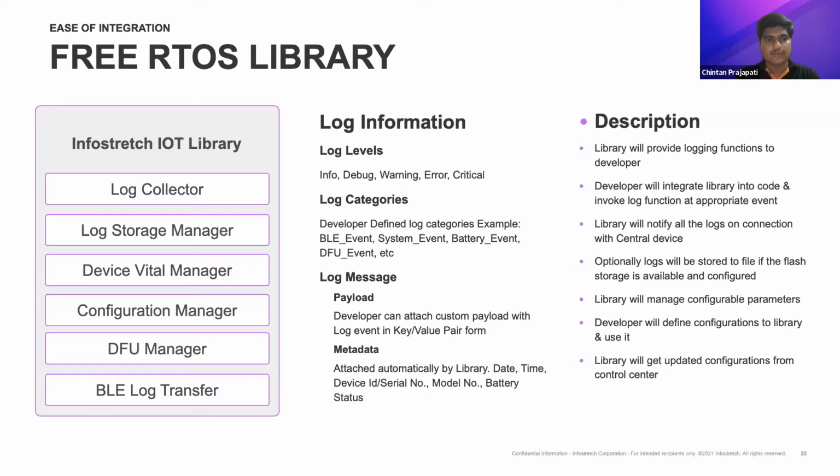Device vital manager: whenever we collect any event, this device vital manager is mainly responsible for collecting common metadata, such as CPU usage, memory usage, and storage. All those common data are captured by the device vital manager. Configuration manager: there are a few configurations we need to capture, such as at what frequency we need to capture data from the sensor and at which frequency we need to sync the data. Then there are the DFU manager, the device firmware update manager, and BLE log transfer, which is responsible for transferring data from the microcontroller to the mobile application.